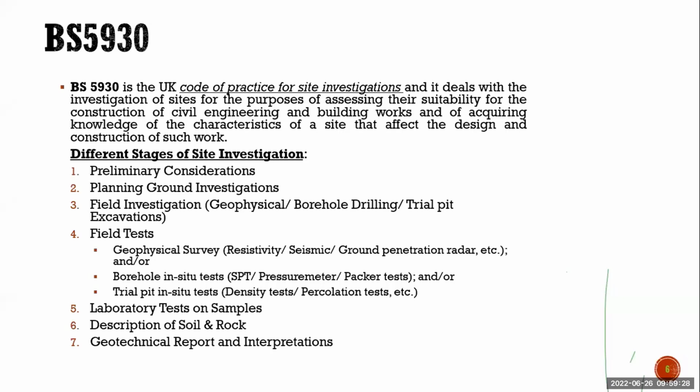In the reconnaissance survey, you just go to the site and see what problems are on the site. Let us say you find a slope, or drainage issues, or a landslide, or the site is flat with no problems. Or next to the site, whichever building has been constructed, is there any cracks on the building? So this kind of information can be gathered in the reconnaissance survey.